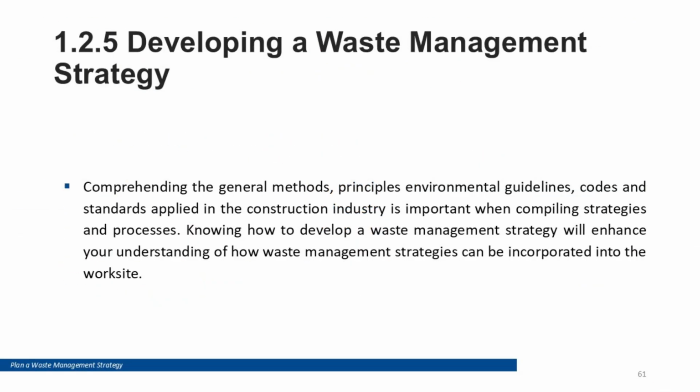Developing a waste management strategy. A waste management strategy should be practical and site-ready. It typically includes waste types expected on the job and likely quantities, waste prevention actions, including ordering and handling controls, on-site separation and bin skip arrangements, recycling and reuse options, including approved facilities, roles, responsibilities and communication requirements, recording and reporting, dockets, receipts and tracking against targets.